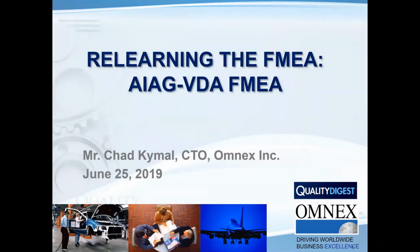Well, as Chad is going to tell you here in just a little bit, the AIAG VDA FMEA has updated the AIAG FMEA document that most of you have probably been using since the 60s. There are two popular formats, the one used by the AIAG, and in Germany, the one used by the VDA. And the new handbook is an attempt to harmonize both those methods. So in today's webinar, Chad is going to take a look at the new manual and some of the differences you need to be aware of if you've been using the old AIAG FMEA document.